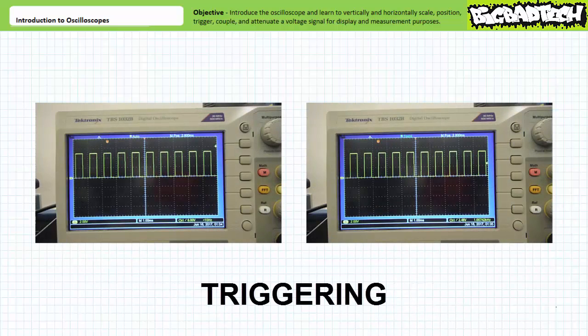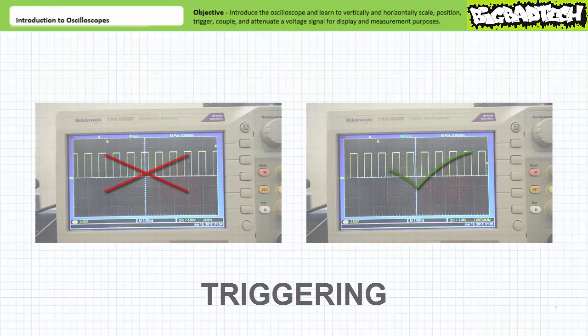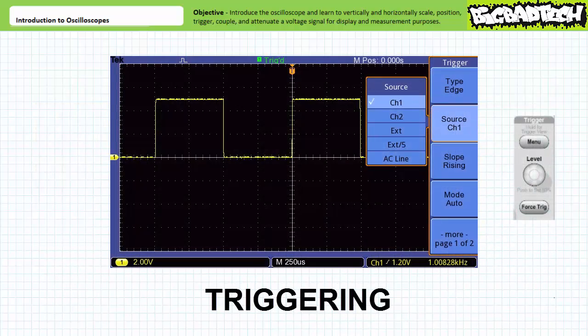In regards to triggering, triggering must occur off an event that actually occurs on a regular basis. If you're triggering off an event that never occurs, or does so on an infrequent basis, the oscilloscope just picks a beat and plays a tune that may not be the song you want. An oscilloscope triggering properly inside the range of the waveform under inspection will hold still and let you get a good look at it. Additionally, make sure the oscilloscope is triggering off the channel you want.